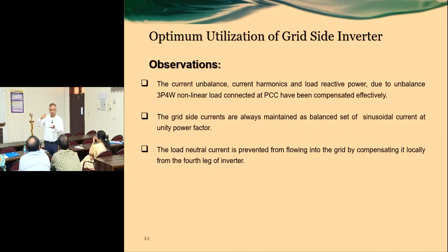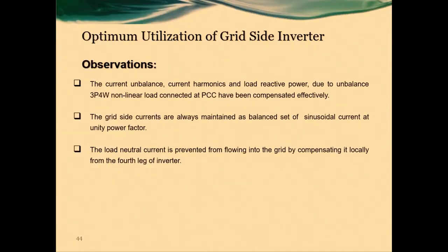That capacity is right now being exploited, but in future you have to definitely plan for different matters also, because if you are installing renewable power, you cannot inject into the system unless you have a plan for evacuating it. Similarly, if you have a utility scale charge station, you need permission also for that. Standards are already given. Similarly, metros are also facing this problem. If they are going to inject some harmonics, they have to pay a heavy penalty. That's why they are coming.